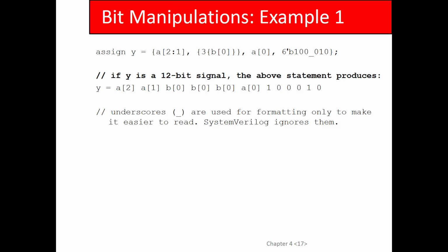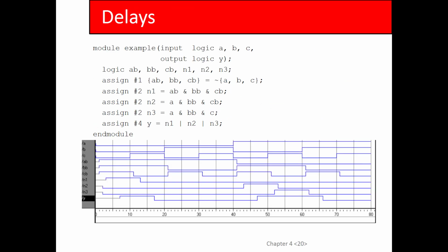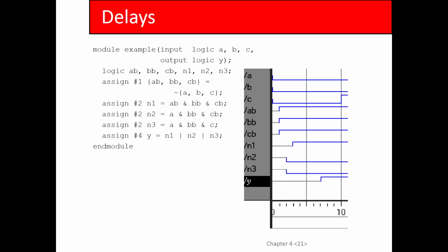Okay, we talked about putting delays in. You can insert a delay into an assign. You can also put delays into always blocks as well, which we covered under the Testbench section.